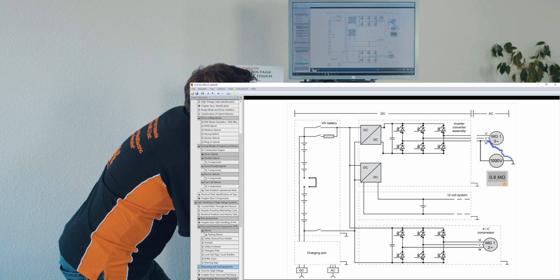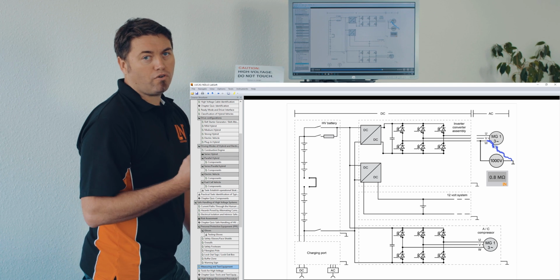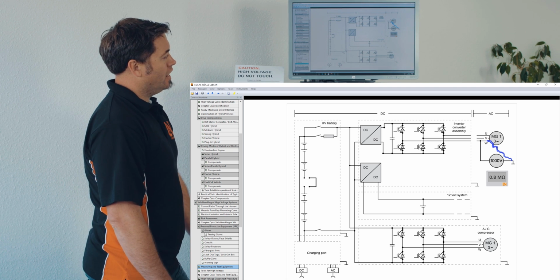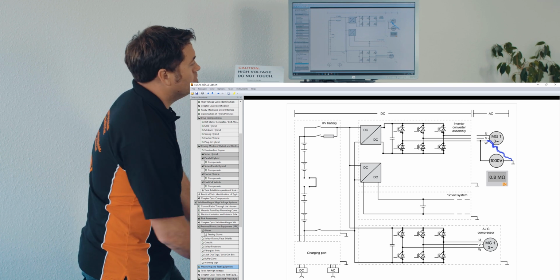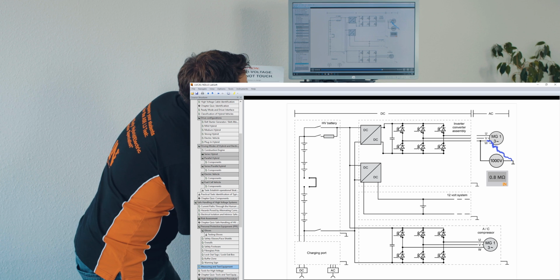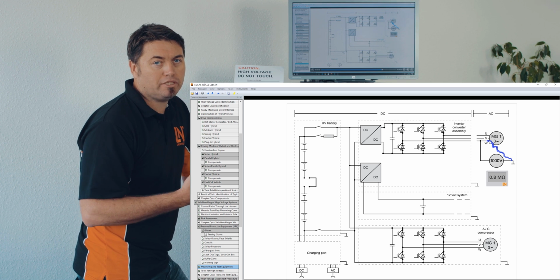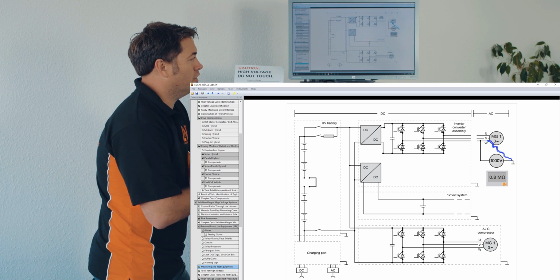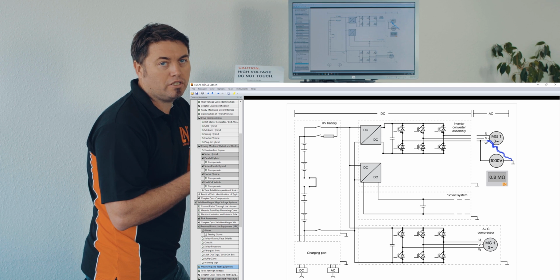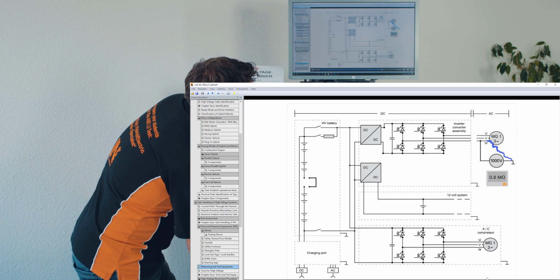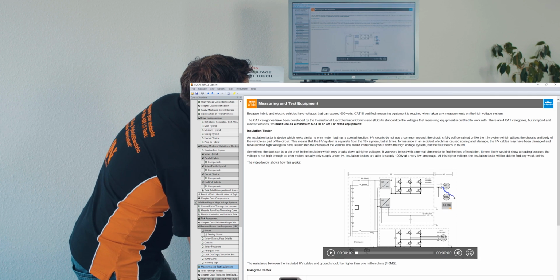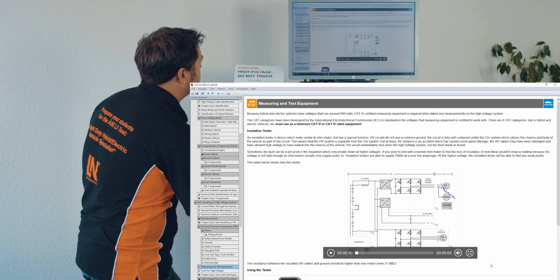Now if we change that to 1000 volts, so now we're putting 1000 volts through those cables, at that point the cables are breaking down. The insulation either has a pinhole or it's been damaged in some way, that once we put it under that sort of stress, then we see the problem to ground. So I'll just show you that as an example of what we would do there.